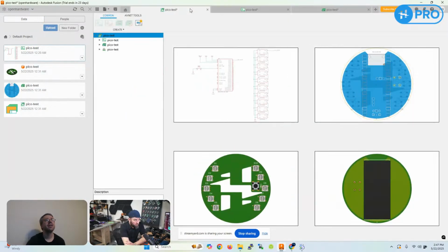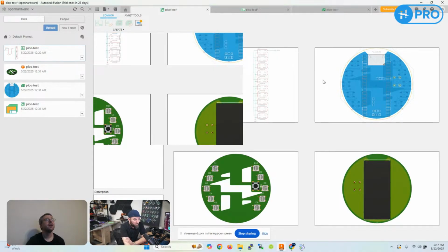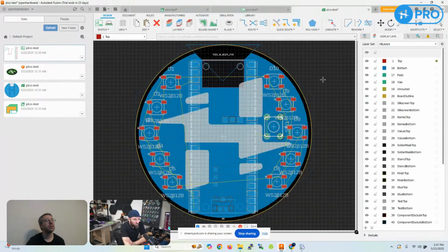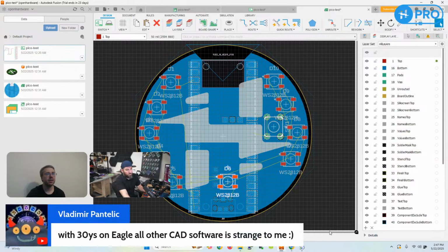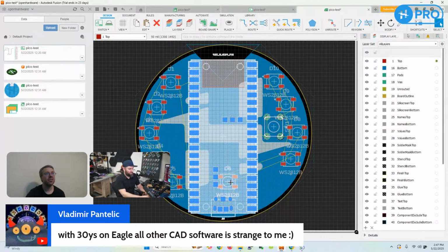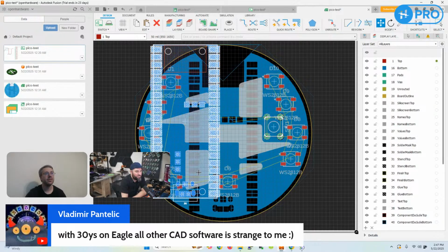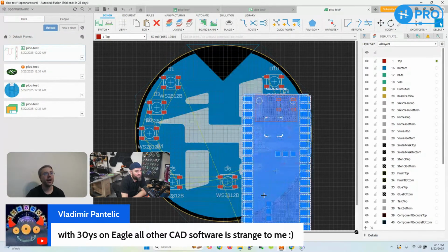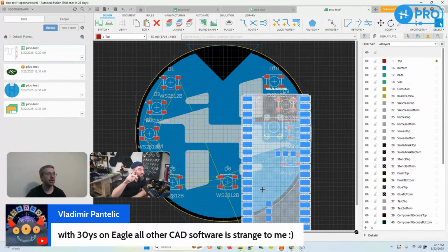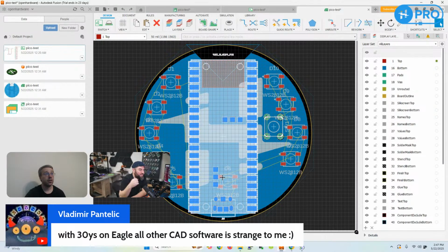The PCB side, I found it cumbersome, to say the least, when I overlapped components on the bottom side of the board. Say I had this switch here, and I put it inside of here, right? And now it won't let me select that part. It's super annoying, because I can't get a hold of the part without dragging this out of the way. And there's no right click, move to the bottom, right click, move to top kind of thing. I haven't figured that out yet.